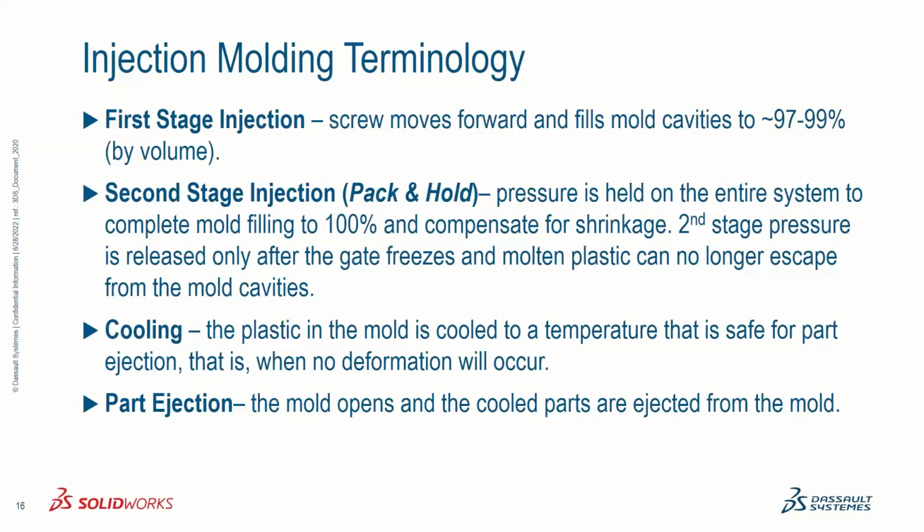At the end of packing, the plastic is still relatively hot. It may not be mechanically stiff enough to be ejected from the mold, and therefore you leave it in the mold for additional seconds to allow it to cool to what is called the ejection temperature, at which point the mold is opened and the parts are ejected. And as I mentioned, the whole cycle takes anywhere from a few seconds to up to a minute.